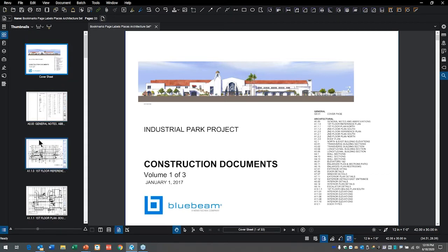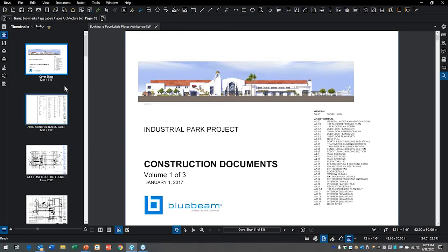One of the things that's also new in this release, the 2019 release of the software, is a little drop-down arrow on the icon to the left of the page label generate, and that is something called page scale. So you'll notice that the pages will have scales down here if they have been calibrated. And so I can tell the software to turn on page scale, right?